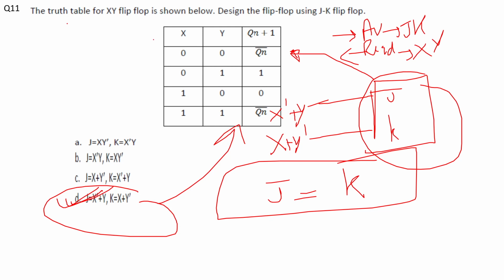So that is the essential functionality that is happening. So you are right. I don't know what got you confused. So you are saying J is equal to X equal to 0 and Y equal to 0, and X equal to 1, Y equal to 1. So you see, if you do the required expression X bar plus Y and X plus Y bar, it reduces to 1, 1 for both the cases. Then toggling is happening. That is the required functionality that is to be done. And then the solution will change, obviously. That's right. Yeah, then the solution will change.